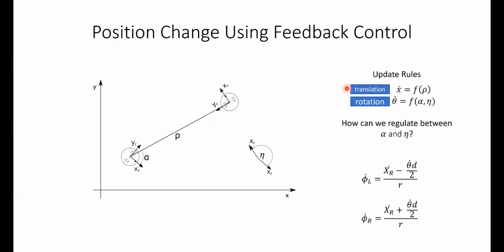And so when you're coming up with values to map your sources of error down to something that your robot is actually going to enact with its motors onto its wheels, the important thing to consider is the relative importance of these two terms. Of course, you want your translation to be related to your distance error, because that's how far you want the robot to move. And of course, you want it to be related to your rotation error, or at least your bearing error, so you eventually start pointing in the right direction.